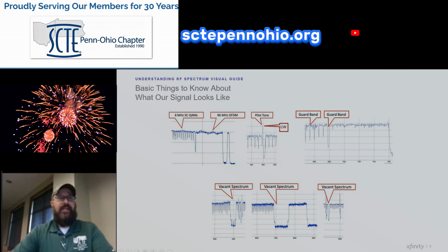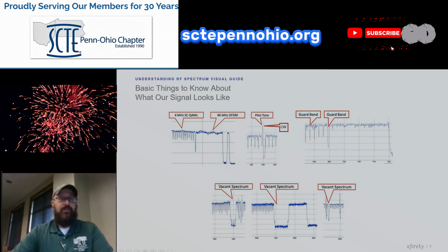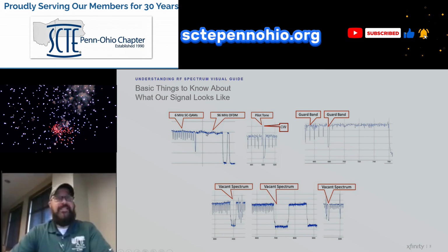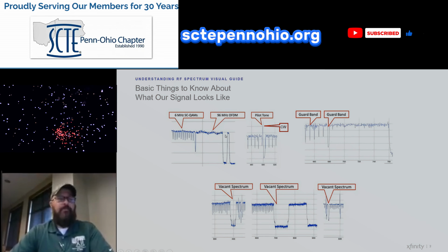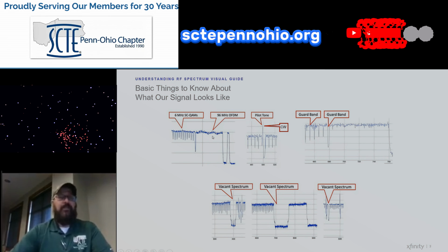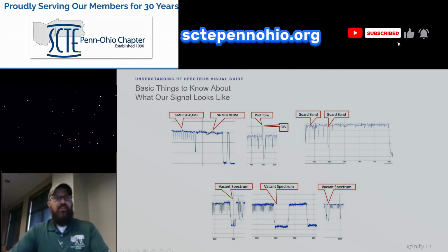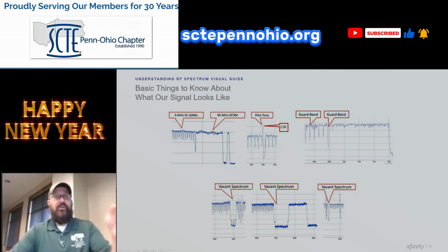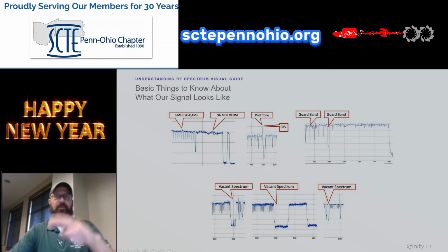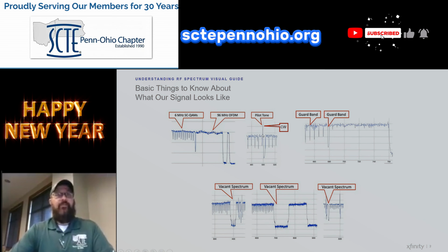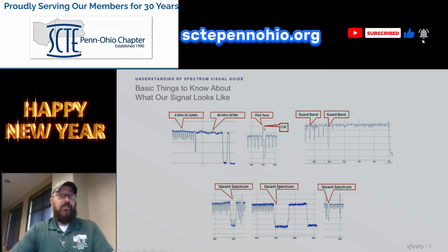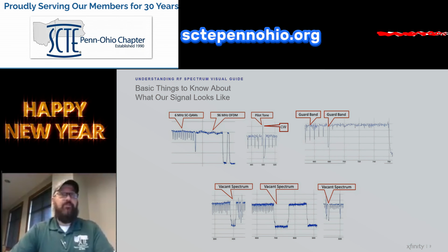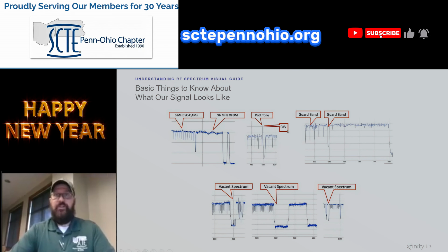In these full band captures, we have our 6 megahertz single carrier QAMs, but then right next to it is a 96 megahertz OFDM block of channel or haystacks. And the tops of it look a little bit different because there are some timing carriers inside the OFDM that kind of sit on top and make the top look a little jagged. Then you'll have other carriers like CW or constant wave carriers that are analog tones, sometimes out there for ALCs or for leakage or for other things.